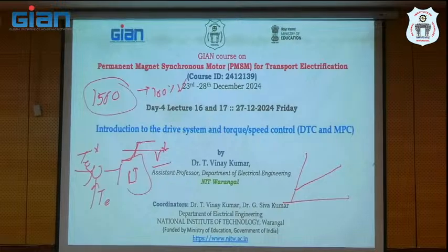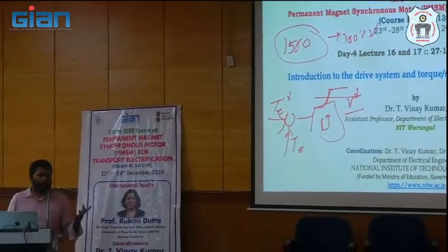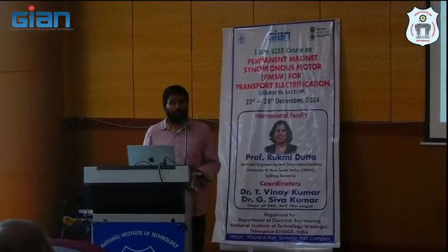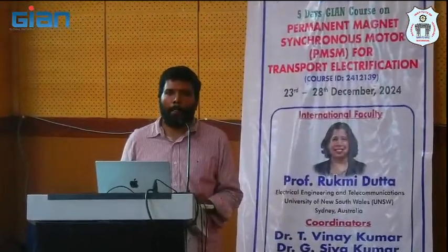See, in control engineering, what is the function of P, what is the function of I, what is the function of D? Why a combination? We should not take P, I and D individually. We need to take the combination. What is the function of P? What is the advantage of P? What is the limitation with P? Proportional. What is the advantage? That is the drawback: error we cannot control through a P controller, proportional controller, but we can improve the dynamic performance. Transient performance we can improve.